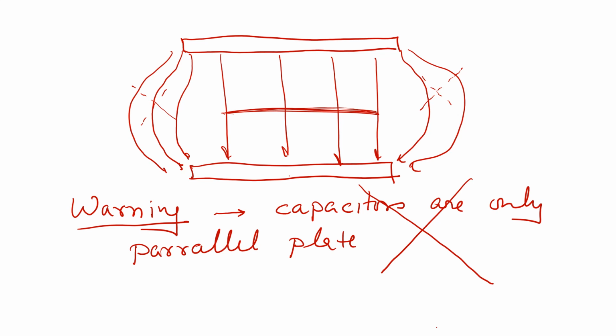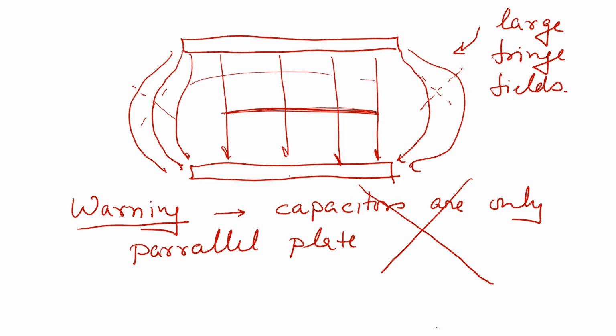In fact, parallel plate geometry has large fringe fields. If you want to use capacitors to store energy, we will later see the energy is stored in electric fields, and we don't want this electric field or energy to leak out of our geometry. Thus, especially for high energy applications, parallel plates are hardly ever used because of these large fringe fields which are present.